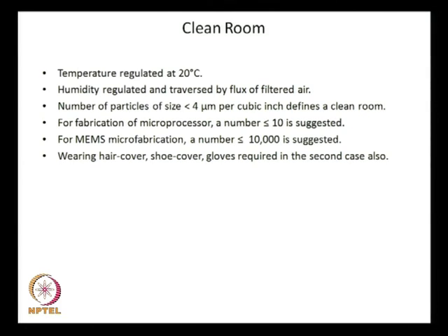The number of particles of size less than 4 micrometer per cubic inch defines a clean room. The number given for a clean room, if it is less than 10, is typically suggested for fabrication of a microprocessor, whereas for MEMS microfabrication a number less than 10,000 is suggested, and typically wearing hair cover, shoe cover, gloves etc. are required.